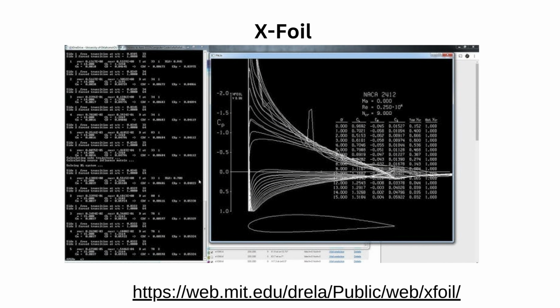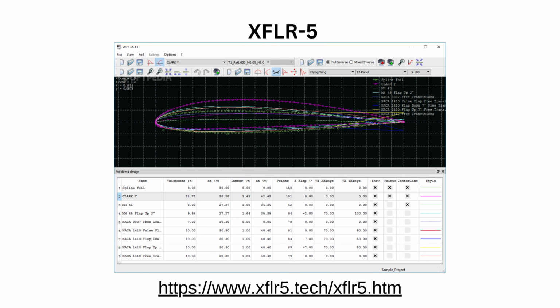Xfoil is a freely available program by Mark Drela that's perhaps the most popular tool for airfoil analysis. It can predict the aerodynamic coefficients based on the airfoil geometry. While Xfoil is a command line tool, XFLR5 adds a user interface to Xfoil, making it easier to use. XFLR5 also adds additional features like panel and vortex-based analysis of wings and airplane shapes.